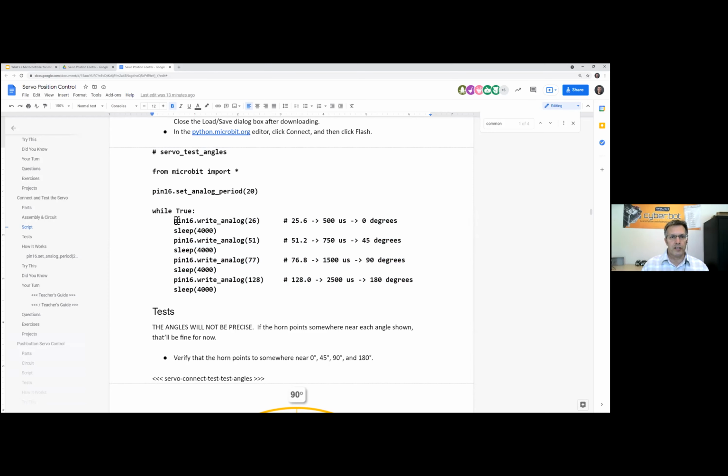And so I'm probably going to have to do this so that we don't go all the way to 0 and all the way to 180 degrees. I thought I could switch to that since we now have a digital servo, but it looks like there are still enough variations that I'll have to go back to the old approach I used with the analog servos, which was to show them maybe 30, 90, and 150, for example, instead of 180, 0, etc.